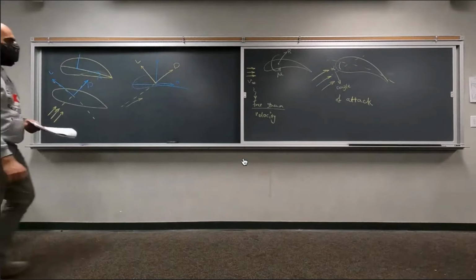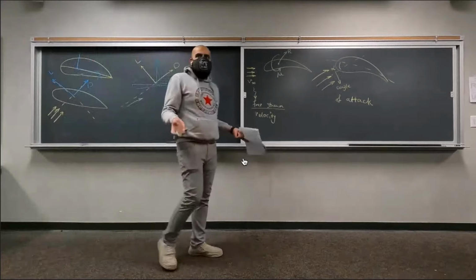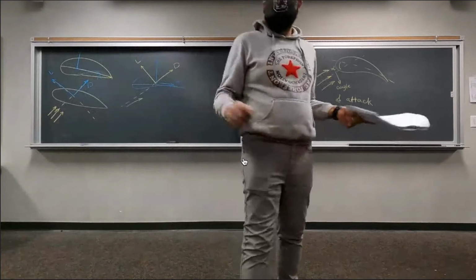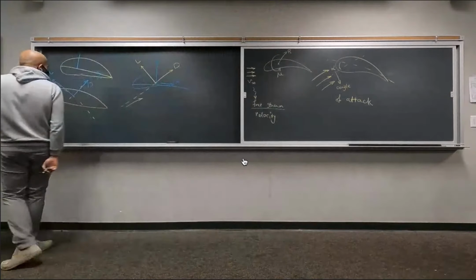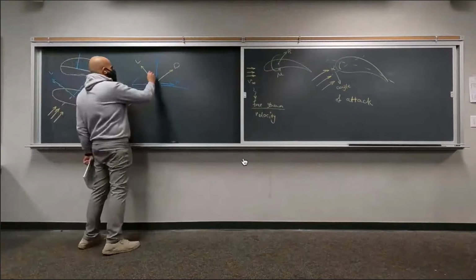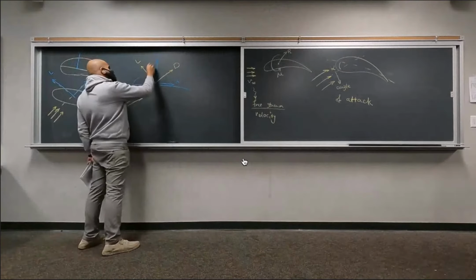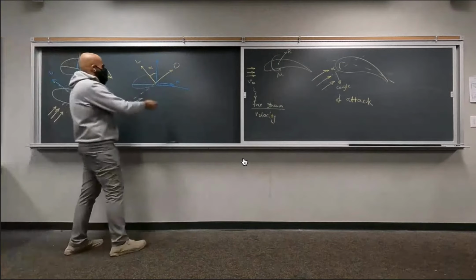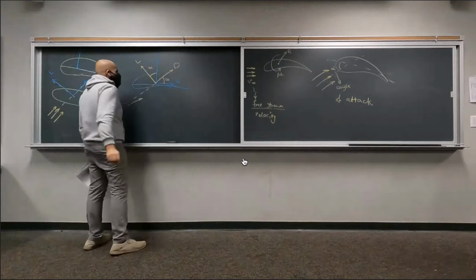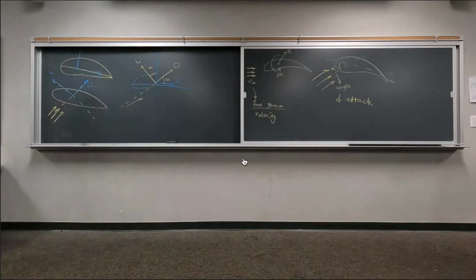Any guesses? We have only introduced one angle so far, so that should be it, right? You don't even need to think about it, because we only have one angle. So angle of attack, right? If you just do some trick observation, visualization, whatever, the angle lift makes with your normal force is going to be alpha, and the angle your drag force makes with axial force is the same as the angle of attack as well.